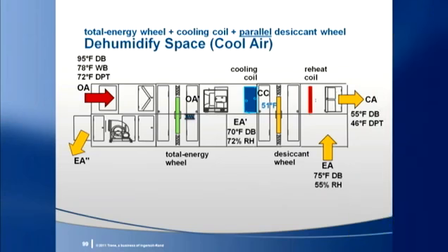In this configuration, the more heat transferred by this downstream device, the less moisture can be transferred. So if neutral air is required, a parallel plate exchanger might be a better choice, unless the cooling coil is unable to achieve the required dew point.